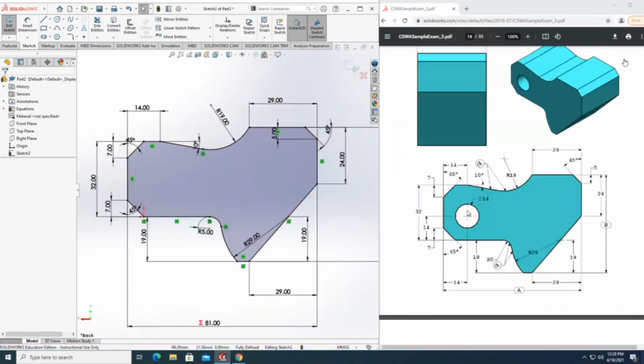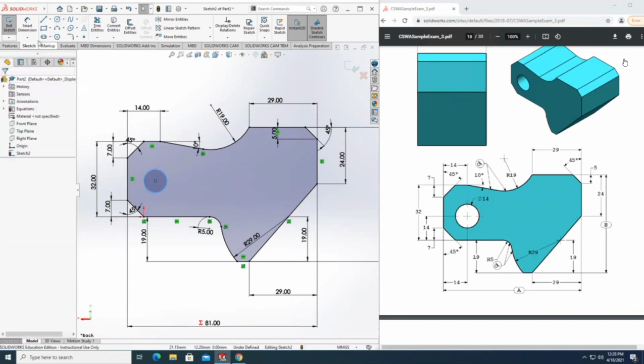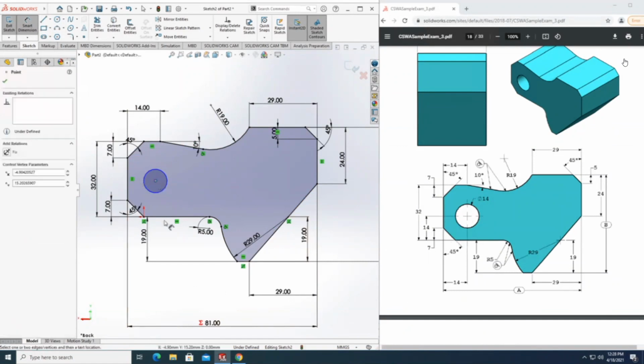Now we just want to do this hole at this point. You can extrude it and then do the hole in an extra step, but let's just get it over with at this stage. We can create a hole, a circle, somewhere at that region, click OK. We can now dimension it. So if we look at the model, they dimension the center relative to this line edge segment and then this segment. So that's what we're going to do.